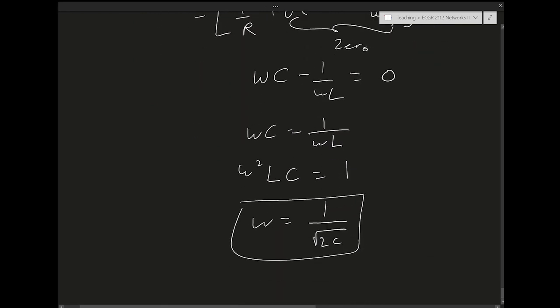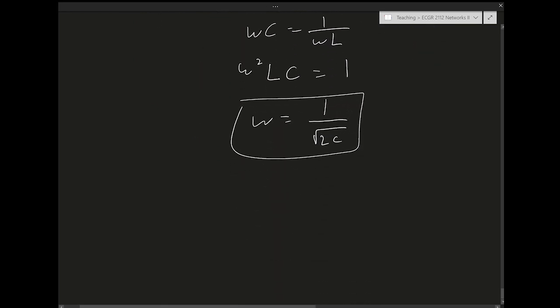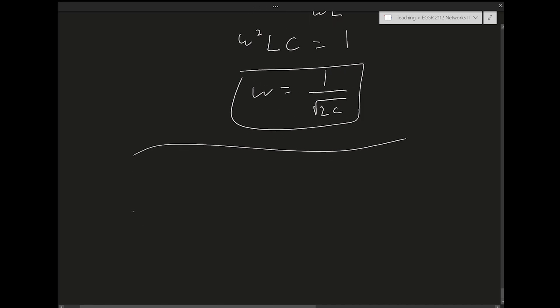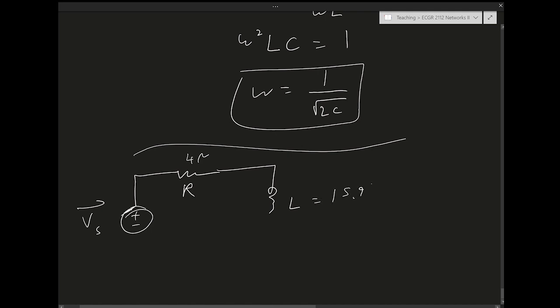Okay. Another example of a phasor diagram is one with the series connected circuit. So if I have Vs, and drawing phasor diagrams is a skill that you need to develop. Hopefully we will do that in future homework, but this is a skill you are expected to develop and be comfortable with. So let's do it for a series circuit. I have here R, let's say 4 ohms, L 15.92 millihenries, and then C 1326 microfarads.